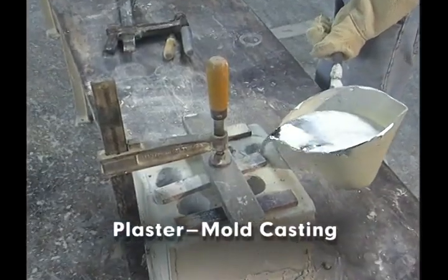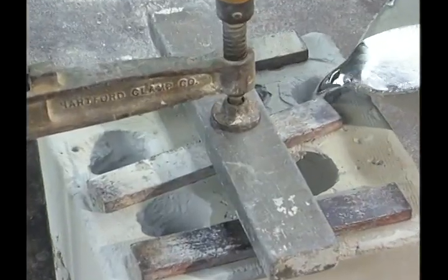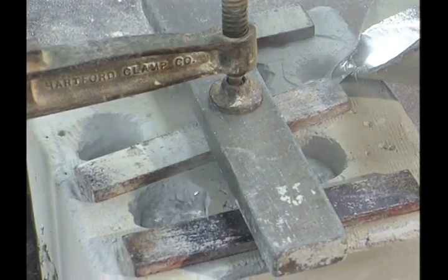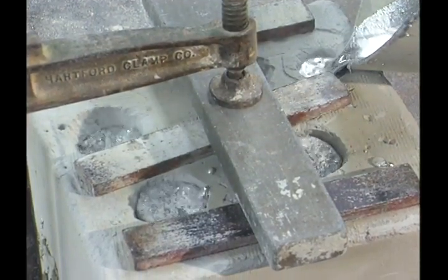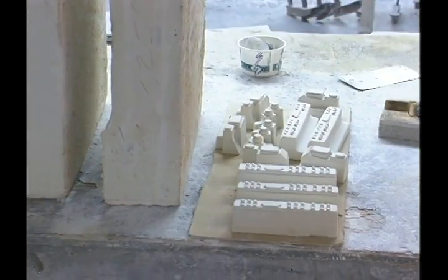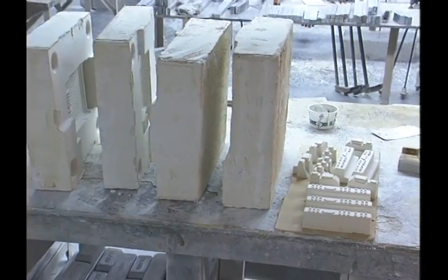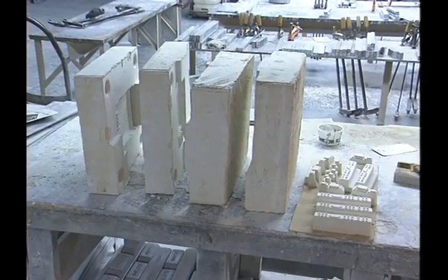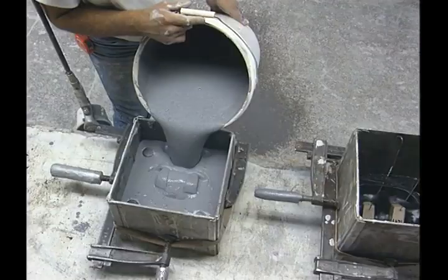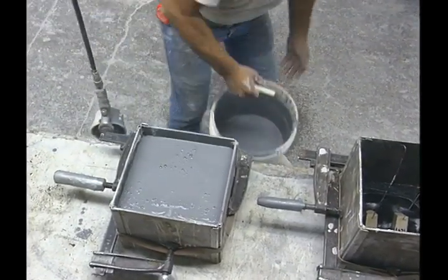Casting in plaster molds is a precision process for aluminum alloy, low-lead copper, and zinc alloy parts. Ferrous metals are unsuitable for plaster mold casting because the molds cannot withstand their high melting temperature. Plaster molds and cores are made largely of calcium sulfate or gypsum and water. Besides calcium sulfate, other mold ingredients may be used to improve moldability, reduce porosity, increase strength, and/or control contraction.